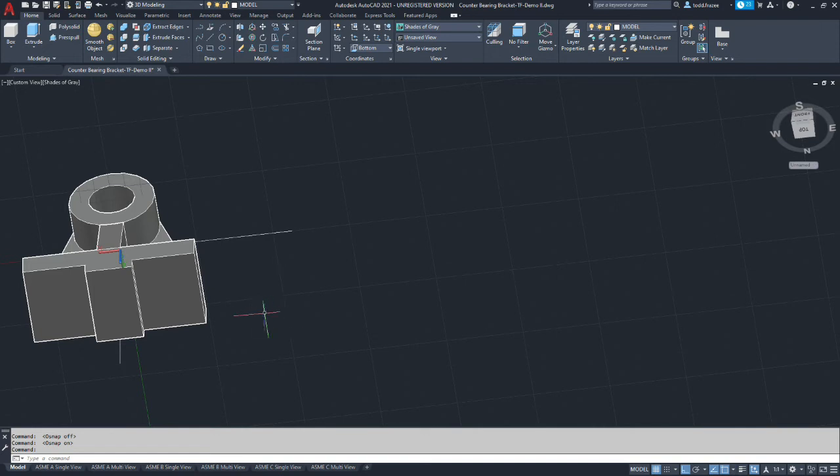The first thing I would like to do is create a line that will give us center. We should be able to pick, with the object snaps, the midpoint of both ends of the keyway boss that we have there. Now we can go to the offset command and set that at half of the spacing of the bolt holes, which is 41 millimeters, and offset that line to either side. So we now have our hole centers defined in one of the two axes.